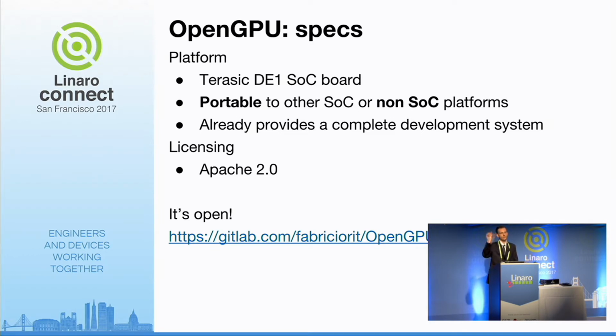You don't have to put bridges or communicate with USB, PCI, or anything like that. It is much easier. But it is not restricted to it. You can get a non-SoC board, a complete FPGA without, in this case, an ARM CPU, and develop it, transferring the data through it, but it's not a restriction.